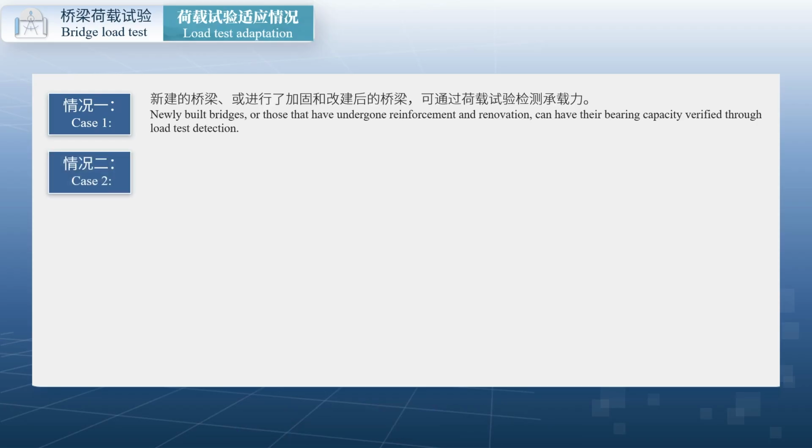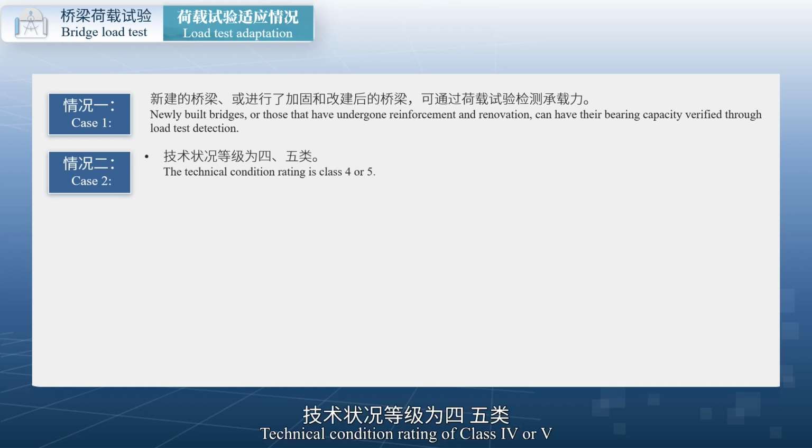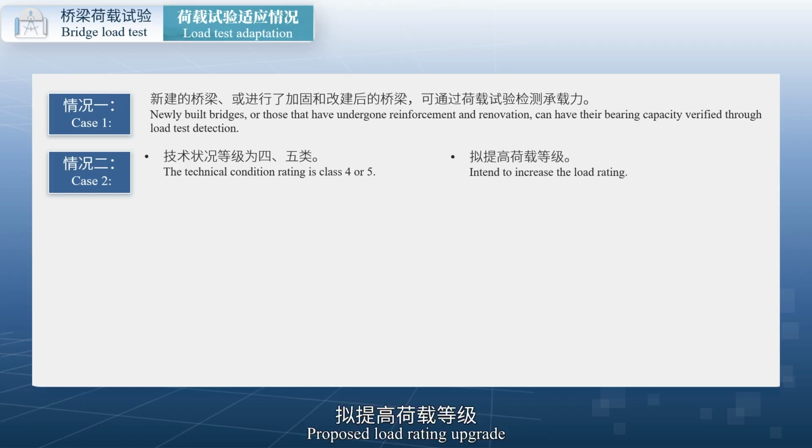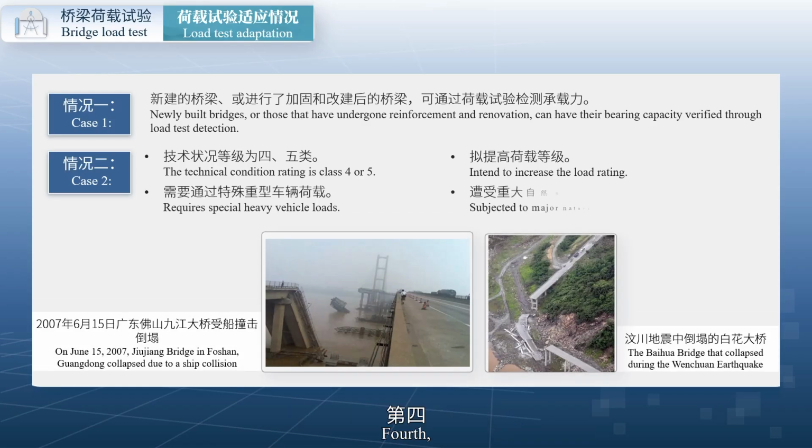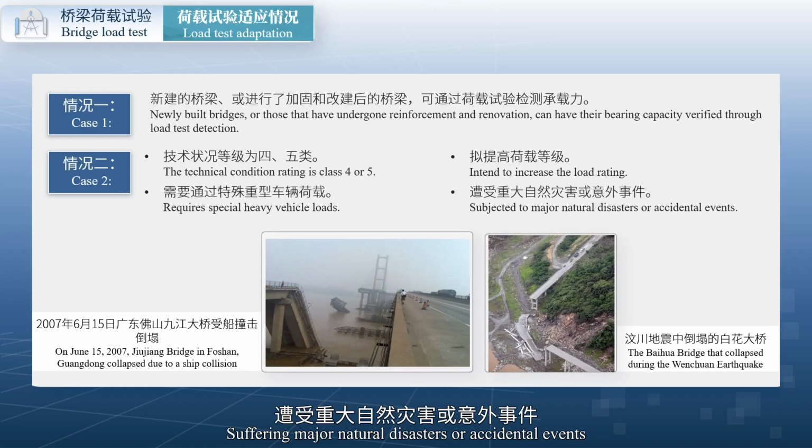Condition 2. Among in-service bridges, if one of the following situations exists, load tests can be performed. First, technical condition rating of class 4 or 5. Second, proposed load rating upgrade. Third, requires the application of special heavy vehicle loads. Fourth, suffering major natural disasters or accidental events.